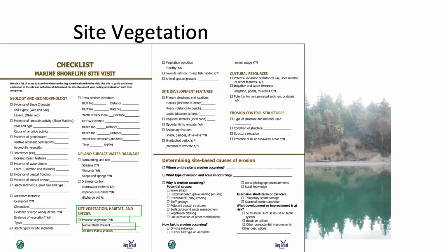We talked a bit earlier about how water is the bad actor in slope stability. So well-vegetated slopes with a broad range of vegetation types tend to be more stable than those that are non-vegetated or have a single monoculture, a single type of vegetation dominating or potentially crowding out other vegetation.